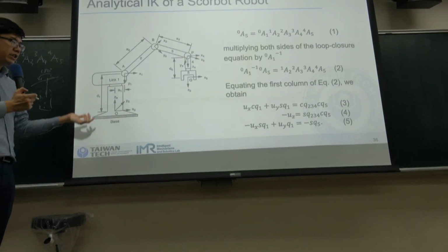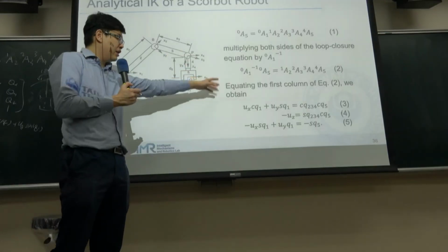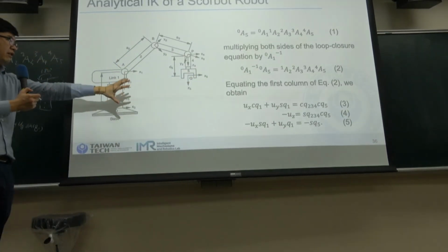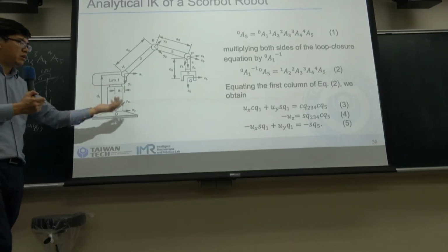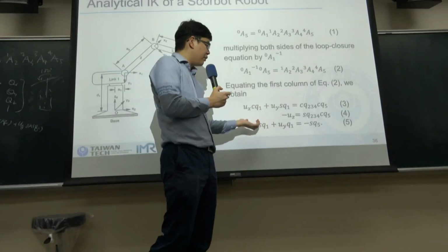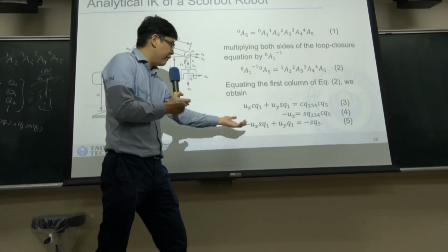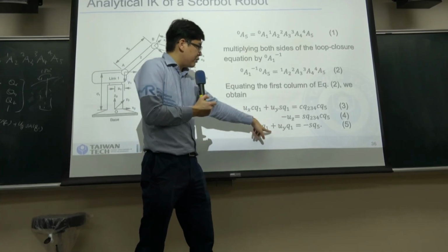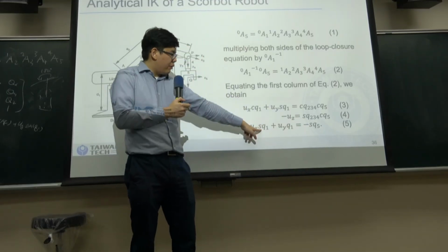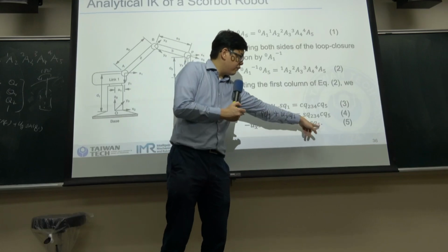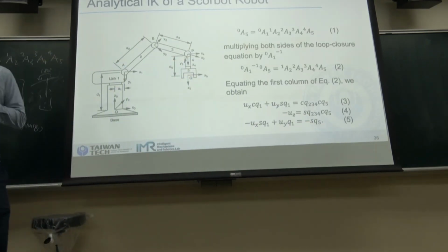for inverse kinematics, it's basically just altering the equations and finding a way to eliminate all the unknowns and leave only one unknown, so you can solve the value. So if you see these equations, once we already know the value of Q1, then we can solve the Q5.